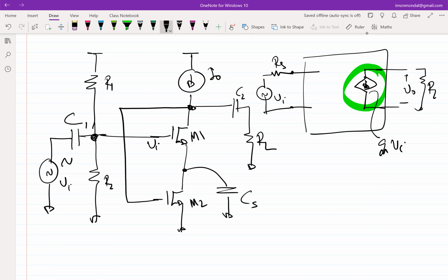Assuming CS is sized properly, at the signal frequency this will be grounded. This will not swing, right? And at zero frequencies, where there is no signal, CS is open and you have negative feedback that is holding the bias together. So at zero frequencies, what is CS essentially doing? At zero frequency, this doesn't exist. I have negative feedback, a constant current source, and things are biased tightly. At signal frequencies, this CS is